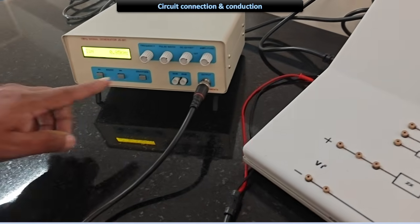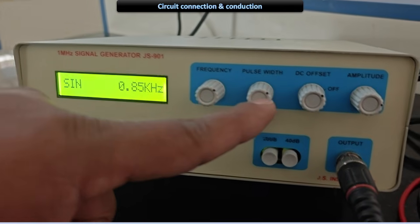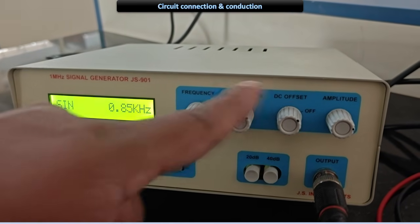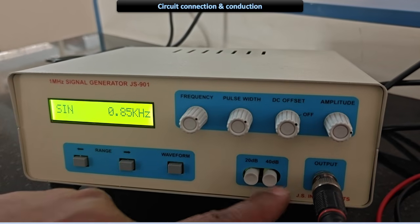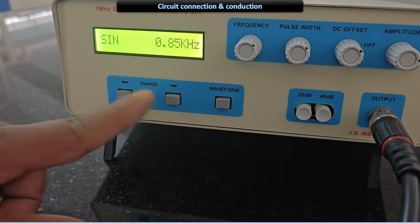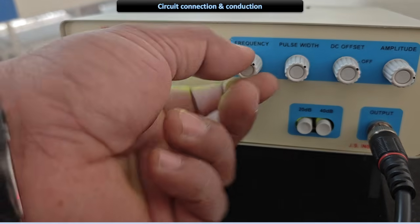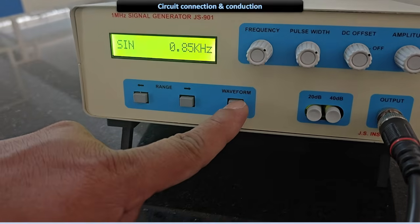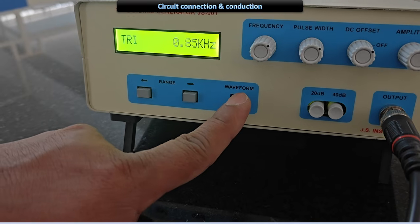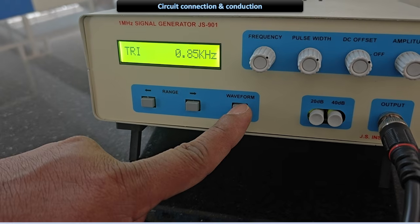Coming to the function generator, here we have different knobs: frequency knob, pulse width, DC offset, and amplitude. We are not going to use pulse width and DC offset. We also have the attenuation options, that is 20 decibel and 40 decibel. We are not going to use those. We have a range setter, which can be used to set the frequency range. Ensure that it is kept at 0.8 kilohertz. And we have different waveforms. Since it is an AC source, we are supposed to keep the waveform to sinusoidal.